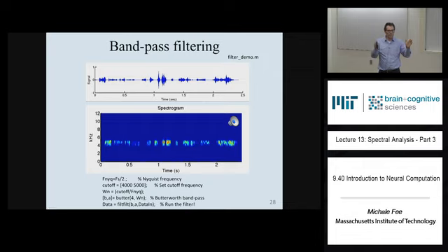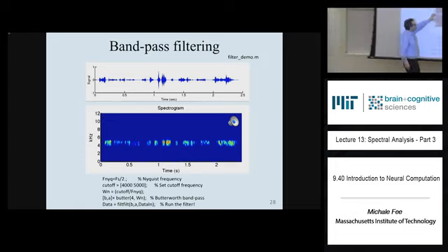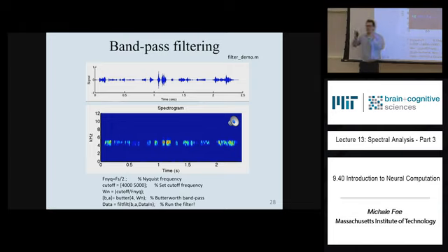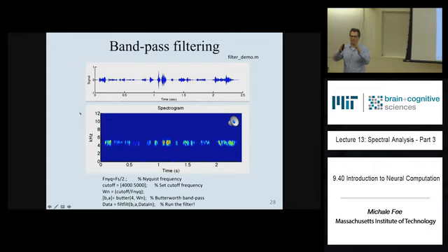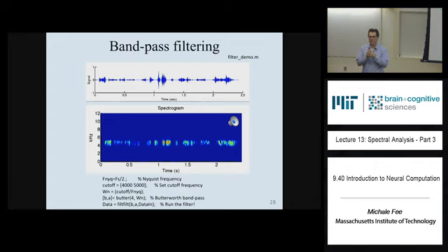Yeah, so take the Fourier transform of your signal, that 60 hertz is one particular value of the Fourier transform, and you can just set that to zero. Because the filtering, in that case, would be knocking down a whole band of frequencies.